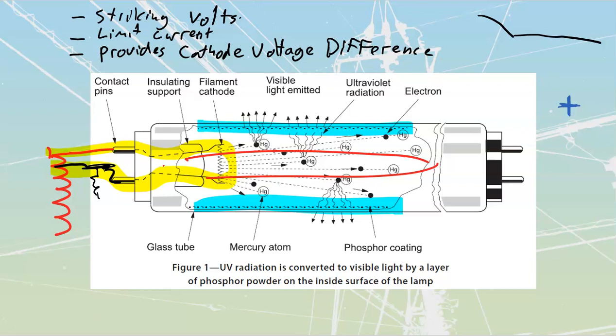And what we're able to do is use smaller amounts of current, fewer electrons, because those electrons are moving so fast, ding, ding, ding, ding, back and forth between those pieces of mercury, which means that we're emitting a lot of UV radiation off of a smaller amount of current flow. This is one of the huge reasons why we have gone to those electronic types of ballasts.